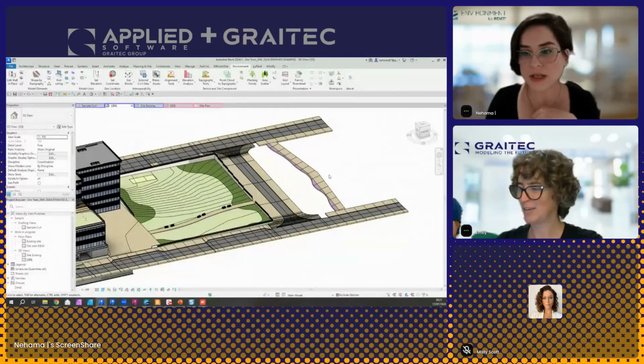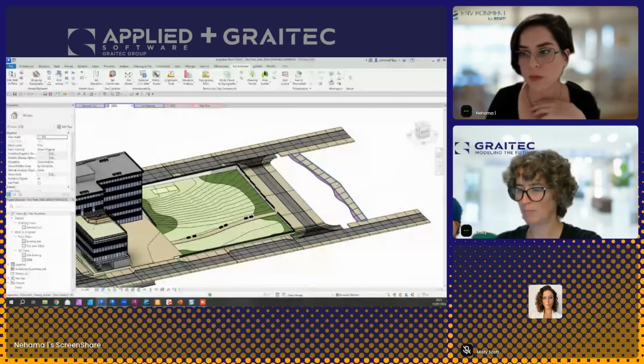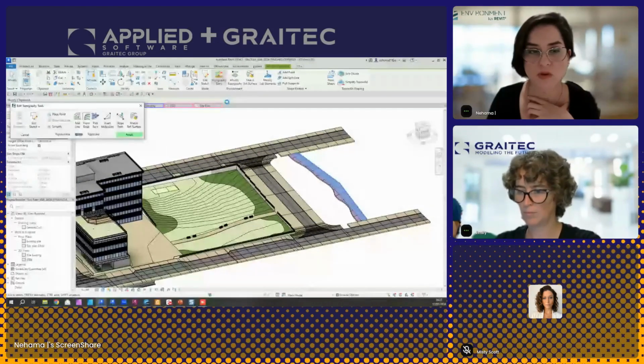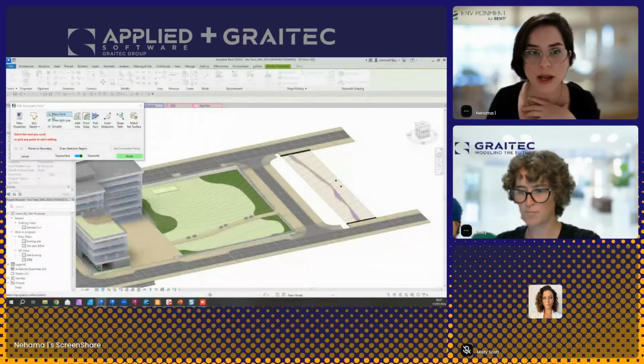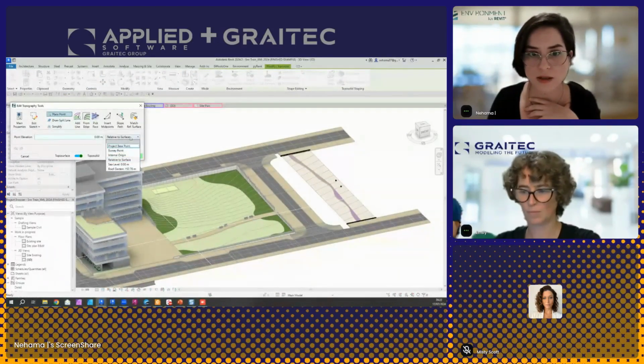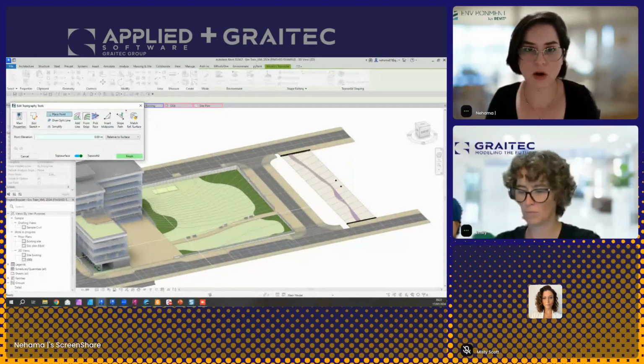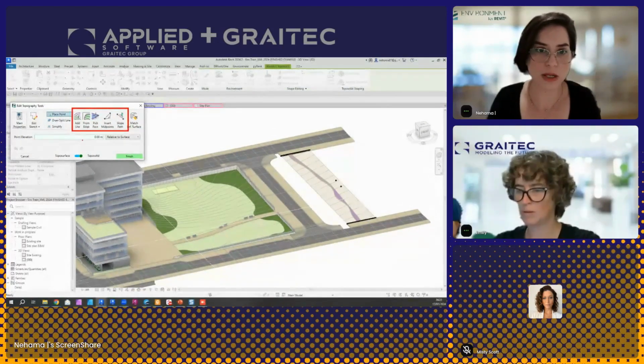Yeah, I just wanted to say you're completely right. With topography tools, first of all, for any topo surface or topo solid you select, in the Modify tab, you'll have the option to either match reference surface or just edit it with topography tools. And if you simply want to add a point, you have the place point, and you can place it relative to any elevation you want, or draw a split line. If you want to place a point in any other way, we can demonstrate many ways, but basically all these are ways to add points.